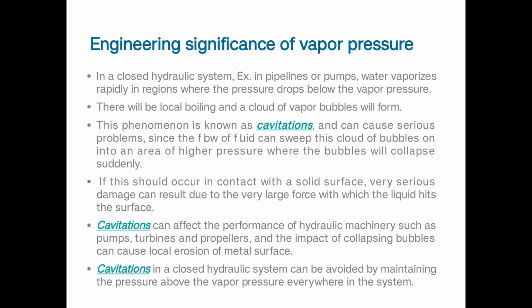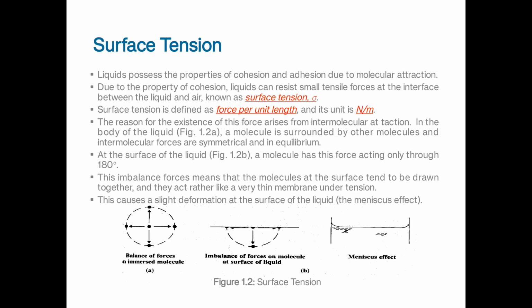We have to maintain a pressure above the vapor pressure every time in such systems. Otherwise, you may see physical damage in those hydraulic systems.